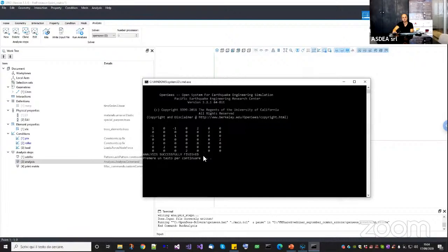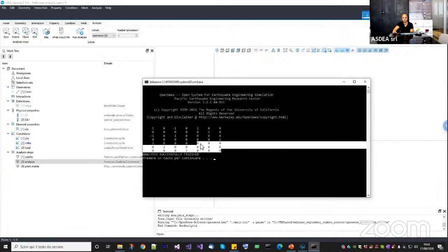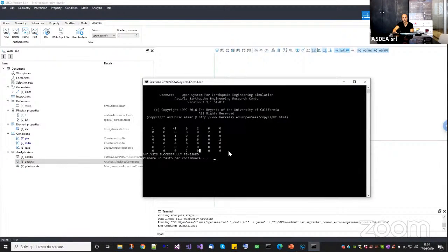But the thing that you have to take care of is that here you have all zeros on the diagonal. So for every equation, you just fill this side of the matrix, okay? And here you have a block equal to the number of constraints times the number of constraints equal to 0. The fact that you have these numbers here will place some 0 eigenvalues on the stiffness matrix. So the huge problem here is that you cannot use an SPD solver.